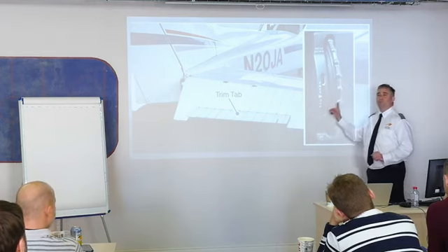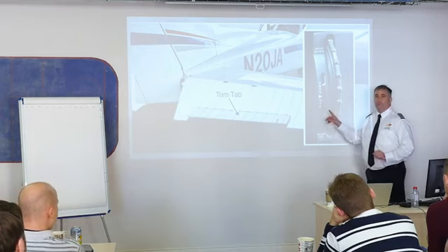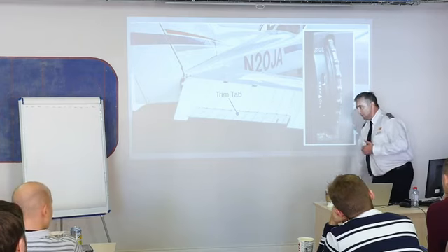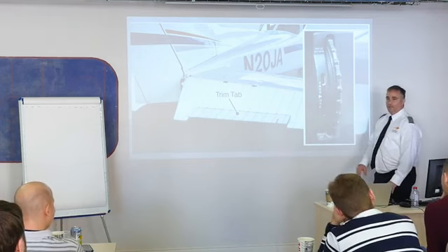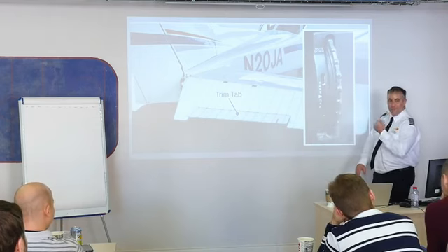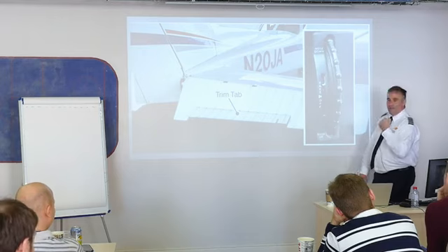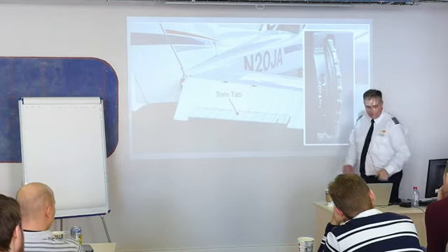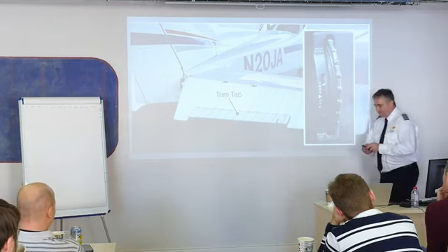But you can't use this to fly the airplane. So don't roll the wheel and expect that it's going to make you climb. You set the climb with your yoke, and then if you have control pressure, you relieve the control pressure. All right, so fly these things properly.